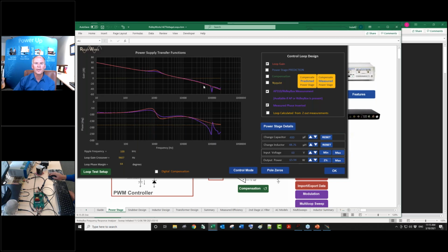Really good job up there. We start to lose the phase at higher frequencies. Complete. Okay, good phase margin, more than 50 degrees. So our little box even gives you the blessing of what the phase margin is and tells you it's good or bad and gives you a little pat on the back so you can feel good about that. Maybe if it's less than 30 degrees, it should say call Ridley Engineering for help. I don't know. What do we notice in deviations here?